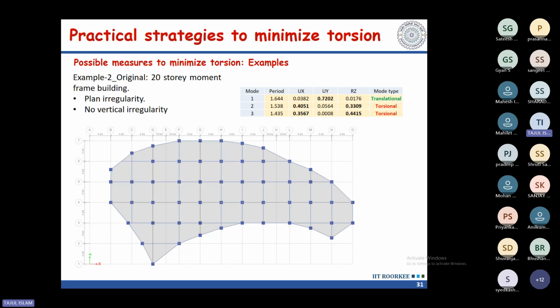In the event of failure, suppose you have designed the building as per the 2002 code, but an earthquake happened and the structure failed, or in the event court cases come, that time your structure will be checked according to the code which was applicable at that time, not the current code.